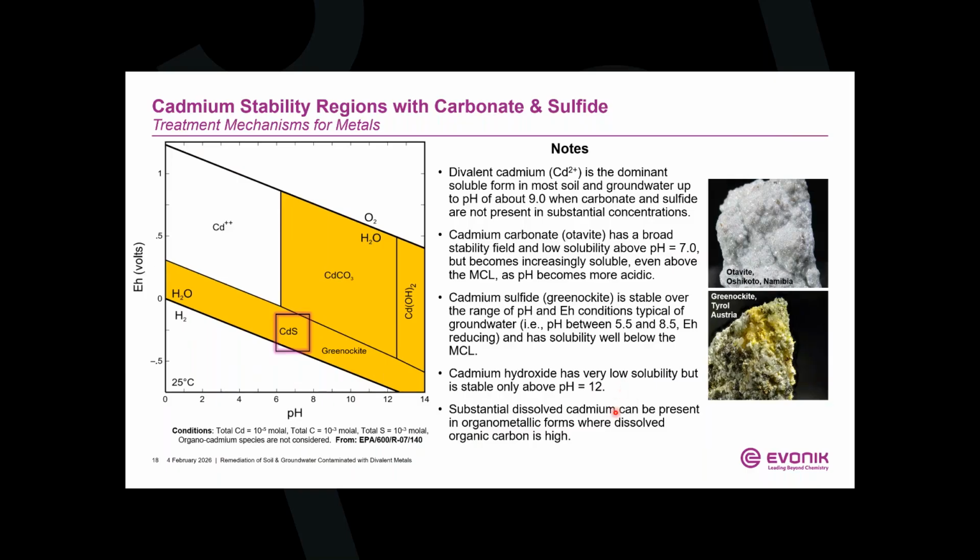Cadmium hydroxide has low solubility, but is only stable above a pH of about 12, so kind of irrelevant in terms of treating cadmium in soil or groundwater. Also note substantial dissolved cadmium can be present in organometallic forms, particularly in environments where you have a lot of dissolved organic carbon. Over time, bacteria process the carbon and deal with the cadmium. They try to detoxify the cadmium by attaching a side chain to it.